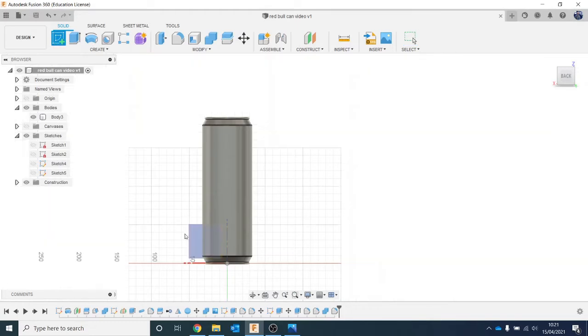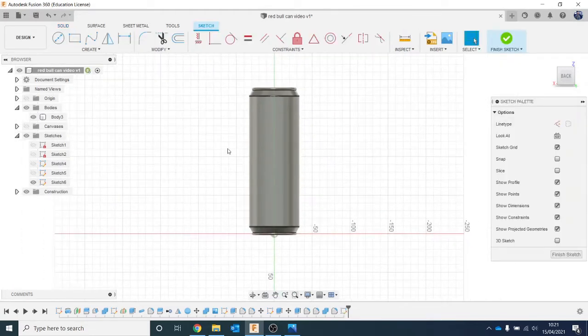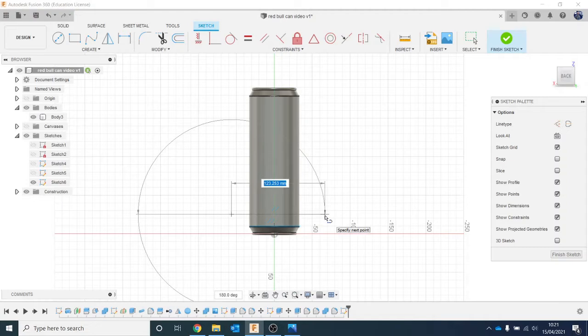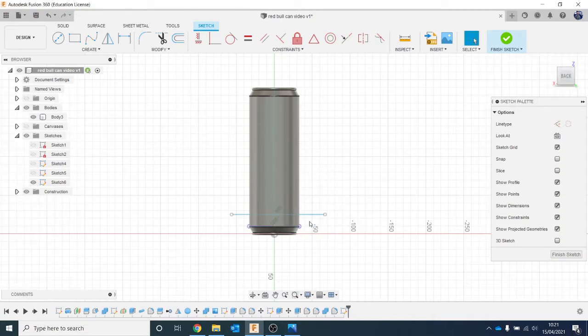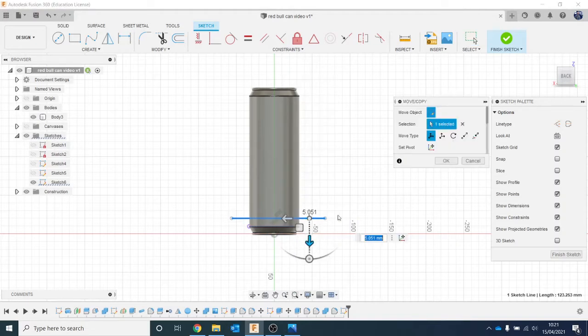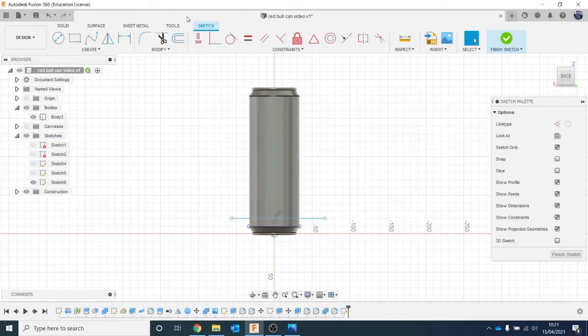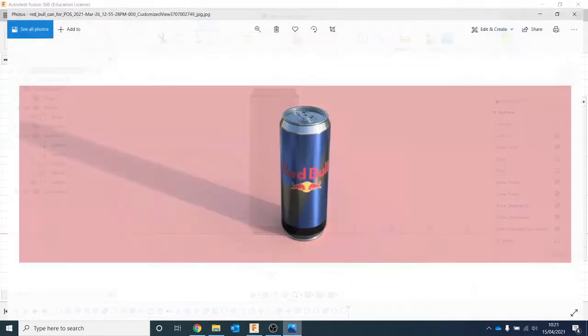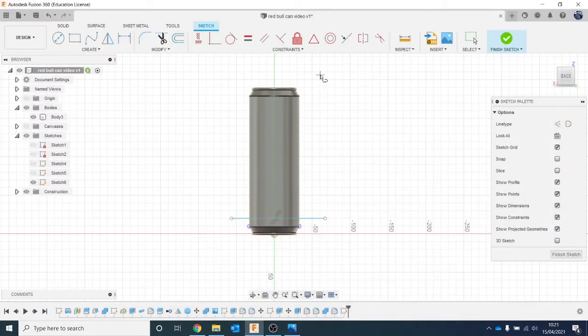Let's create a sketch on this plane. I'm going to do a couple of lines, hit L. First of all, we had just a line coming straight across, so let's just do that one. That's a little bit high, so let's right click and move and bring it down just a touch. Last time I found this quite fiddly, just trying to get the right angle of the line, so let's come across like that, and then see if we can move there.